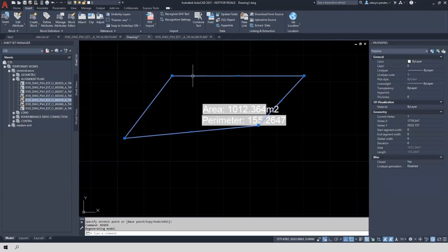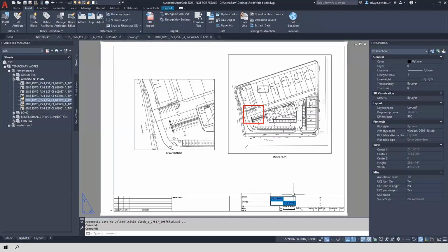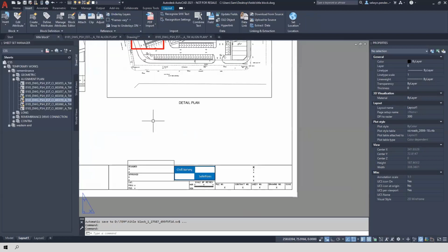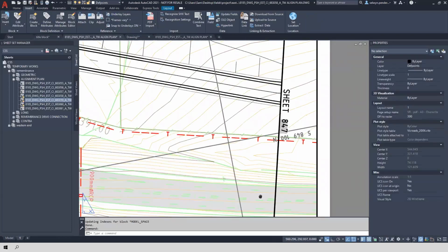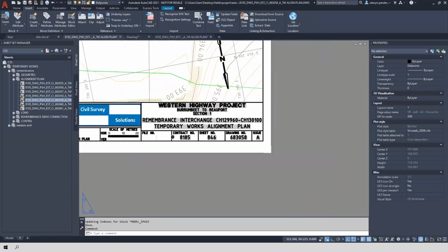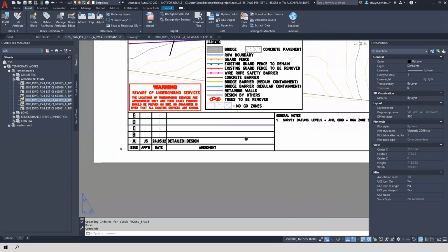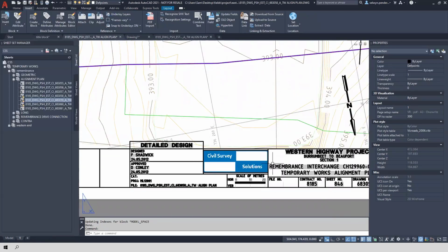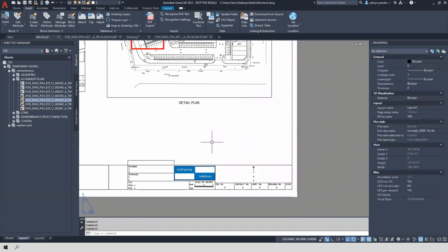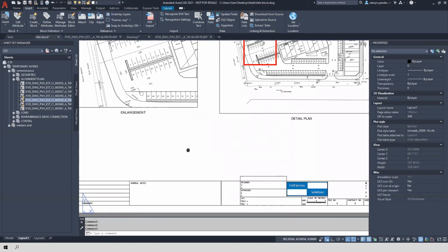We're going to now take a look at a title block. What we've got here is just a basic title block that I've created. I have no entries in here. Normally, if we have a look at this title block, you'll see that we've got fields for everything that's in here, and that's associated with a sheet set. So the fields are reading the information from the sheet set that it's associated with. But what we're going to do on this one is create some drawing properties